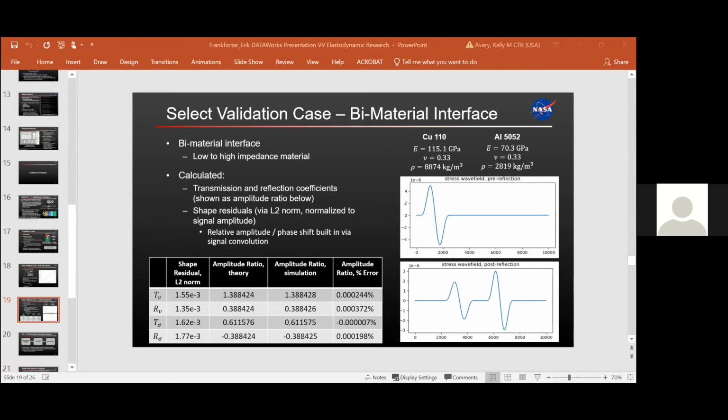One of the interesting things about this is that these cases and these lessons are directly transferable to 3D simulation cases. There are certain assumptions that are built into the 1D model, like a single wave, either pressure or shear, a normal incidence wave going through planar layers. If you create that condition in your 3D model, these cases work out of the box. They just take a lot longer to run. So I find that transferability very valuable. Slide 20, please.